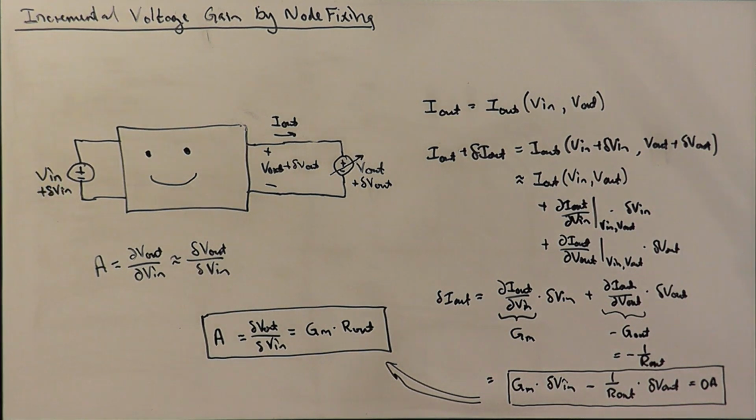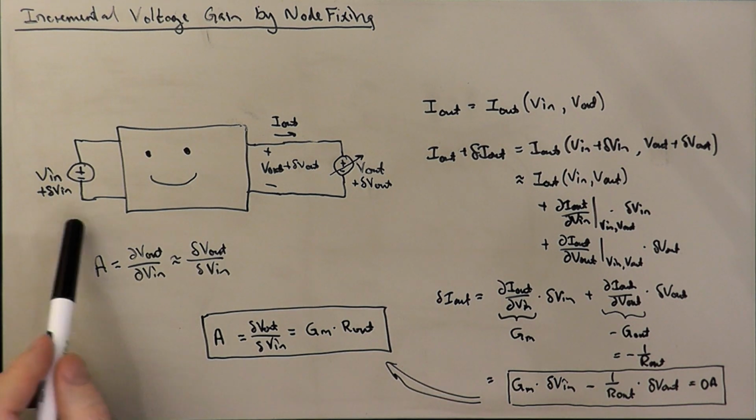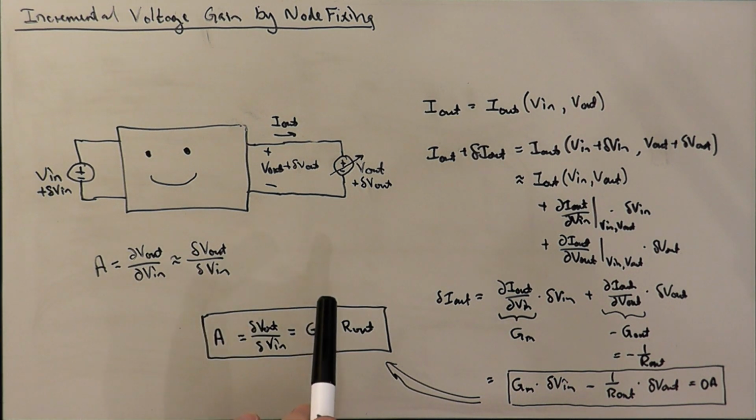And so this is another instance of divide and conquer. Kind of like we had when we had source splitting and superposition. We're using superposition here. This is effectively superposition, saying that we have two components or two sources, and we can compute by superposition the overall result of the circuit by the summation of these two separate components. This is a manifestation of superposition here. But we can compute these transfer functions separately, and the component of delta I out due to each one that we compute, superposed, goes to 0. And the fact that these are computed each with the other source held fixed means that these computations are going to be simplified relative to what they might have otherwise been.